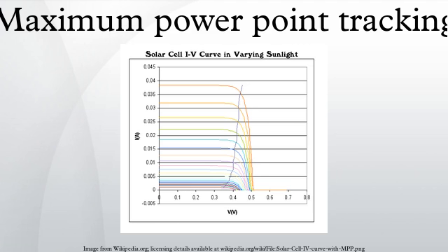Data suggests having one inverter with one MPPT for a project that has east and west facing modules presents no disadvantages when compared to having two inverters or one inverter with more than one MPPT. Efficient east-west oriented PV systems with one MPP tracker, Dietmar Staudacher, 2011.